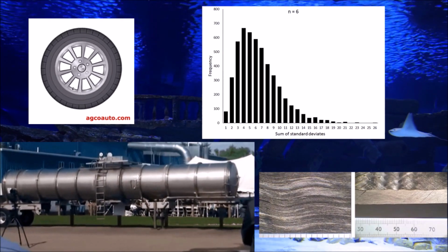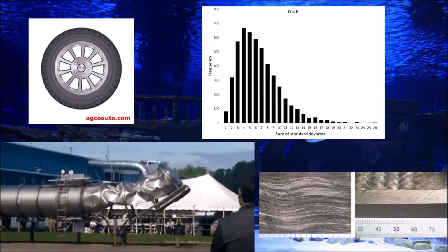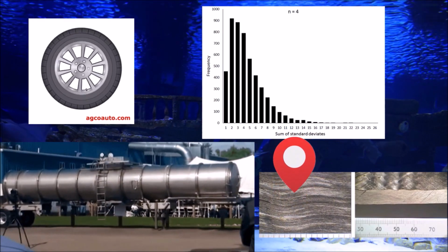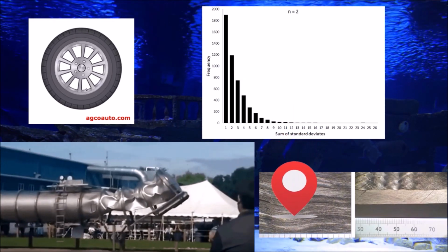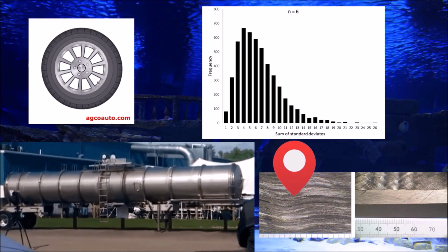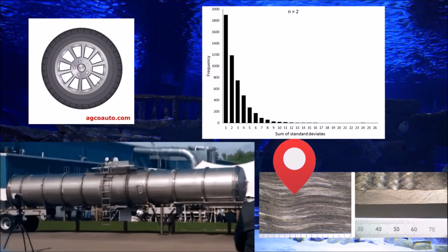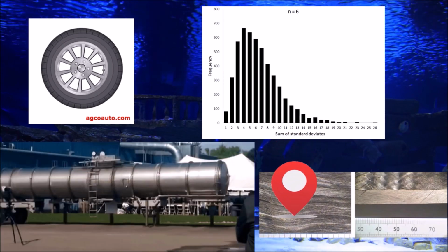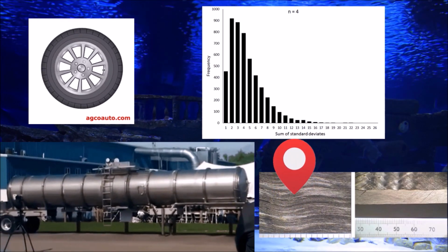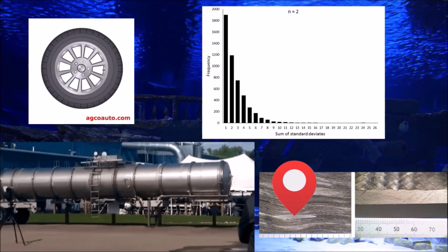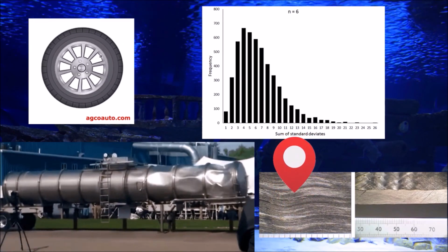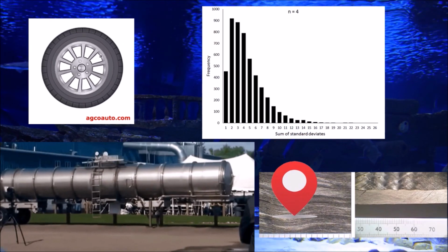The effect of defects on implosion pressure depends on their dimensions, shape, and positions within the cylinder's wall thickness. Delaminations near the inner wall can trigger premature failure, while those near the outer surface might not have impact on implosion resistance. Impact-induced defects can significantly reduce the composite cylinder's implosion resistance.